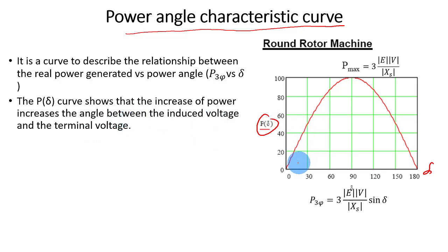It's like a half of a sine wave. So if we increase the power, then the angle between the induced voltage and terminal voltage will also increase. What is delta? Delta, remember, is basically the angle between the V and E. So that is delta, right? So this is what function here.